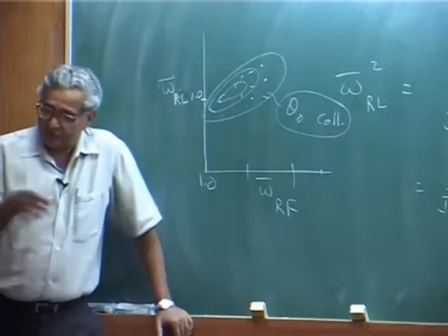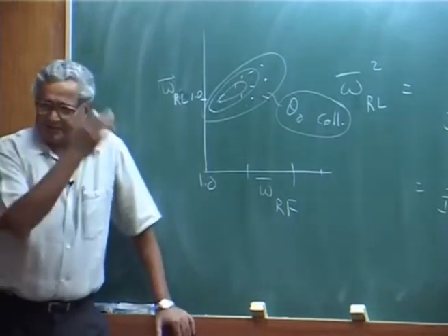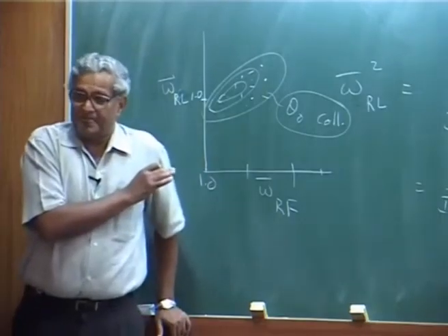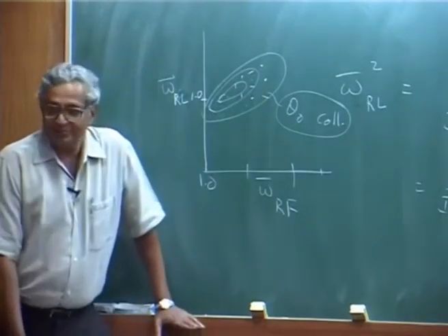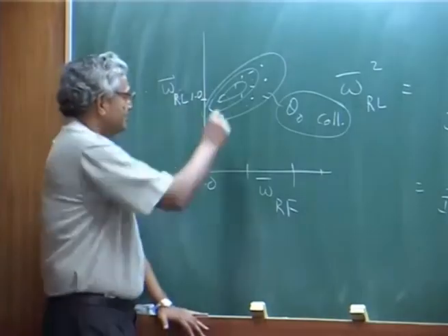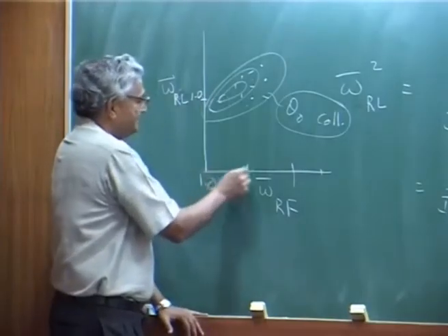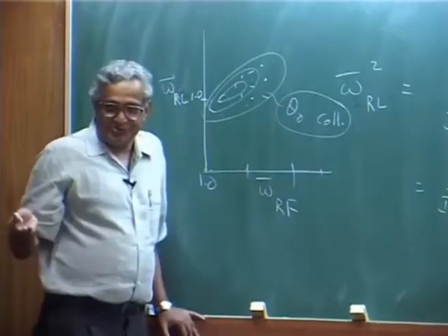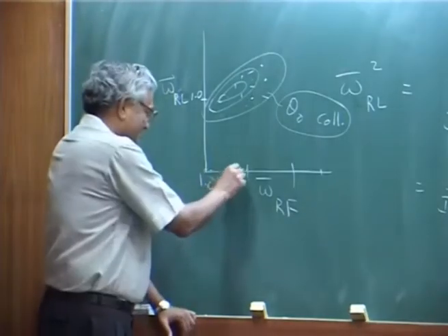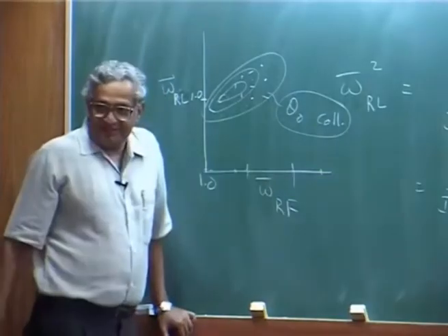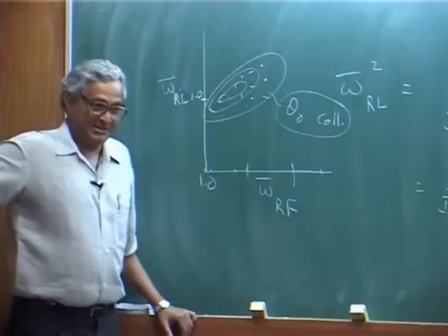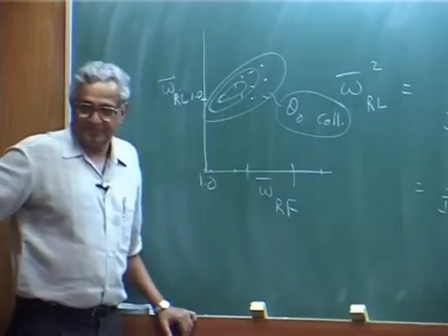And this, of course, lock number, all those things will come. You can draw several curves of this type, and what normally people will say is, hey, let me go, omega flap is around 1.09 or something, you know, this point. You can't take it too far unless you introduce that, what is that, flap pitch coupling.